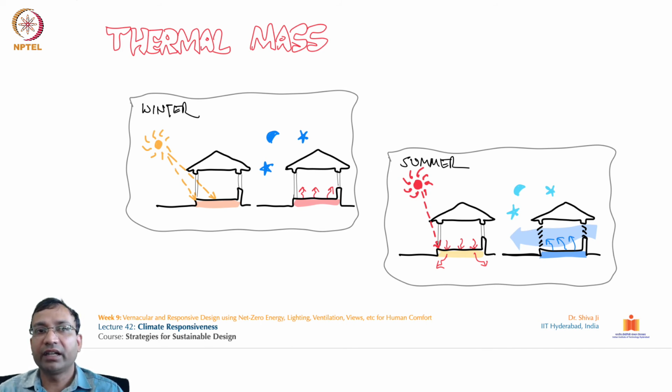So yeah, these aerated or autoclaved concrete, you can see AAC blocks over here. This has 550 kilojoules per cubic meter Kelvin thermal mass storage capacity. So this is one of the preferred materials in recent times, which utilizes the industrial waste output of fly ash in making a bulk of these AAC blocks.